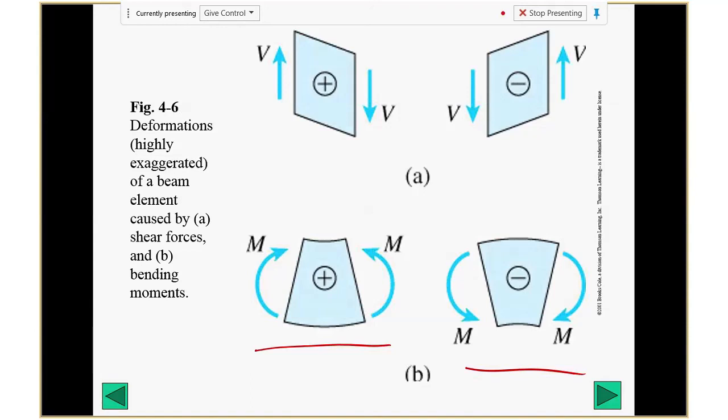So now you see on this surface, this is a positive moment going this way. On this surface, this is a positive moment. They are in opposite directions, but they are both called positive. So it's important whether you look at it this way or this way. The positive definition spatially will be different. The fundamental rule is how it deforms. It's not a positive moment, it's a positive deformation. Therefore, this is a positive pair of moments. So this moment we call positive.